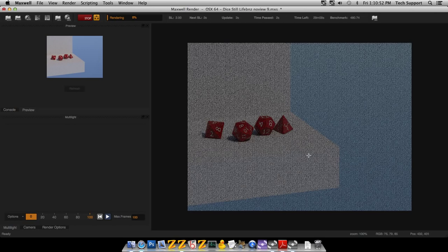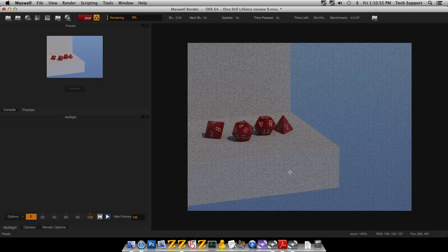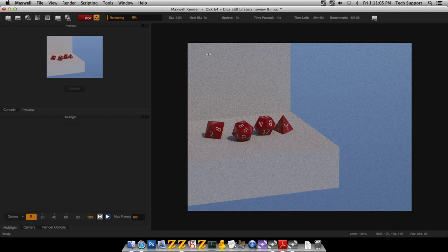And then a render begins. Now, you get the whole image at once, so you don't have to worry about a texture down here at the bottom that you may not have gotten right. A scanline renderer, as you might remember, renders down the screen and kind of leaves you wondering what might be down here. But Maxwell renders your whole image at once. It does start grainy and then becomes more and more distinct as the render cooks.